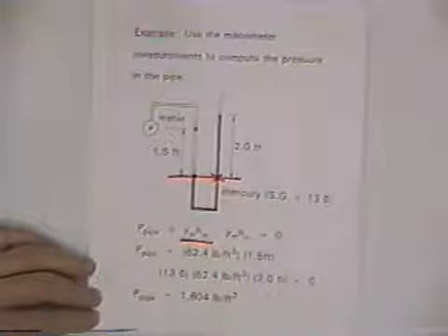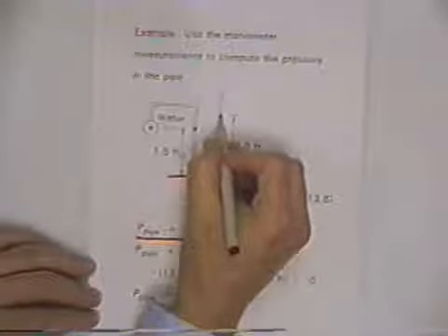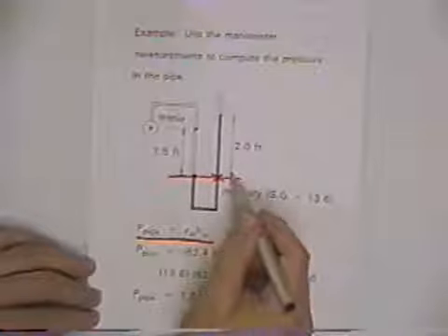Now, whatever the pressure is there, if we go across horizontally to right there, the pressure is identically the same. So we know the pressure there is still that, except now we go up to here. And if we rise, we're taking some pressure off because we've got this 2-foot column of mercury, and so we need to subtract that off.